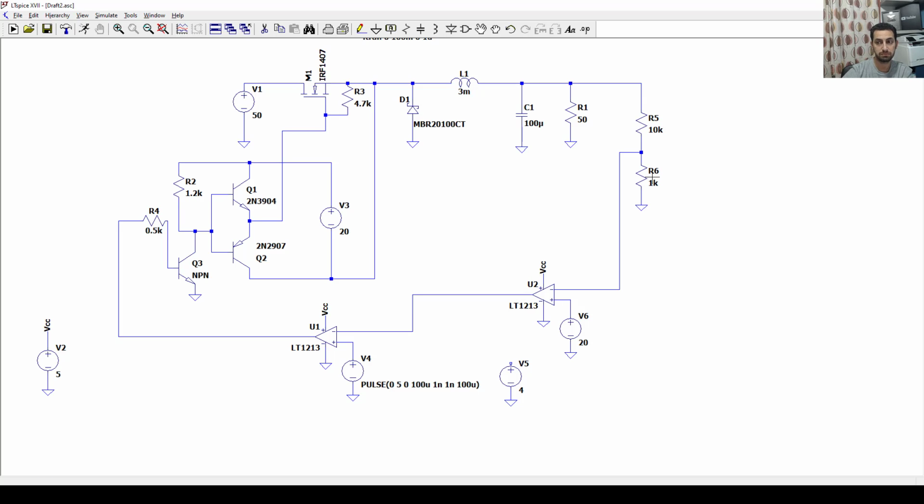So that's why I made a mistake without setting these correctly. So now if this is 50, this will be 5, okay? Because this one is 0.1 division. This is 5, and I have to compare it with from 0 to 5, and let's say 2 volt. 2 volt here will be compared with 2 volt, which means 20. So every value I have here will be multiplied by 10 because I dropped it by 10.